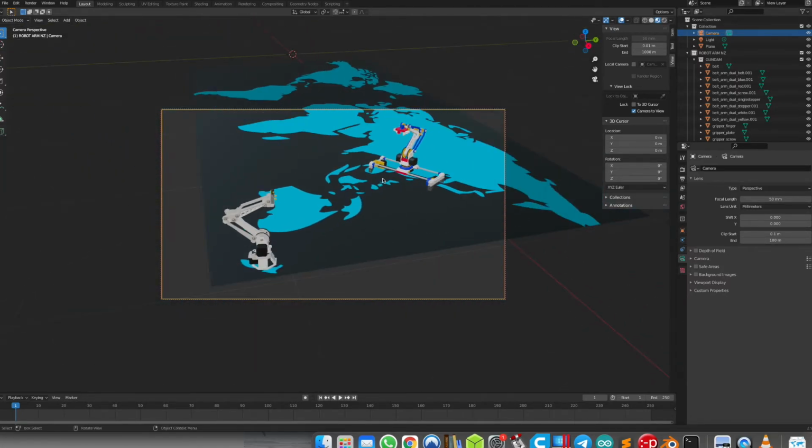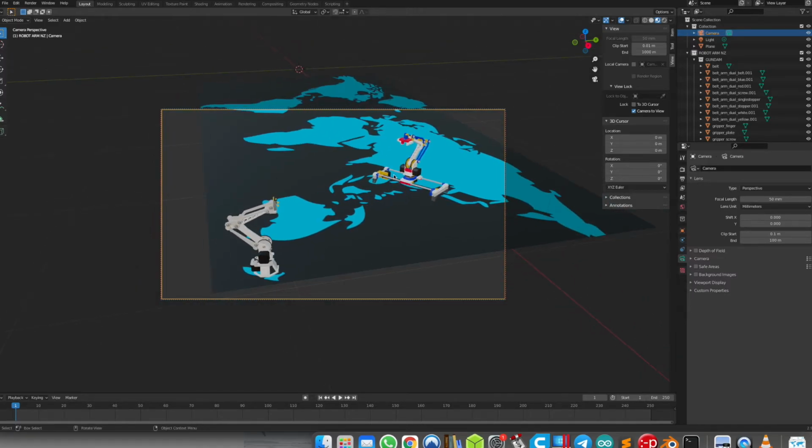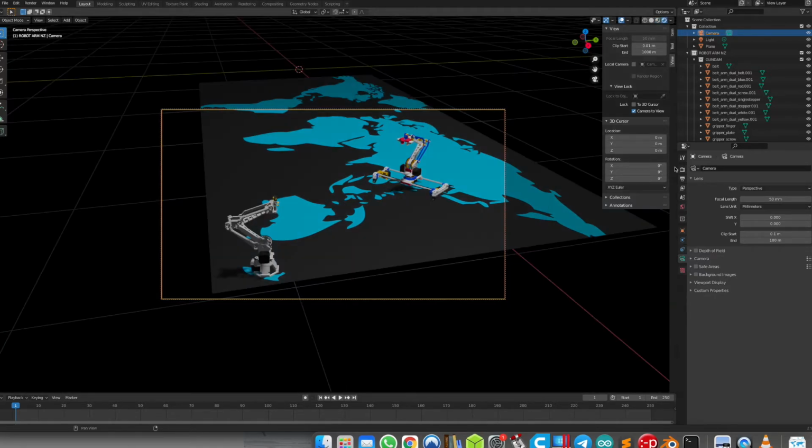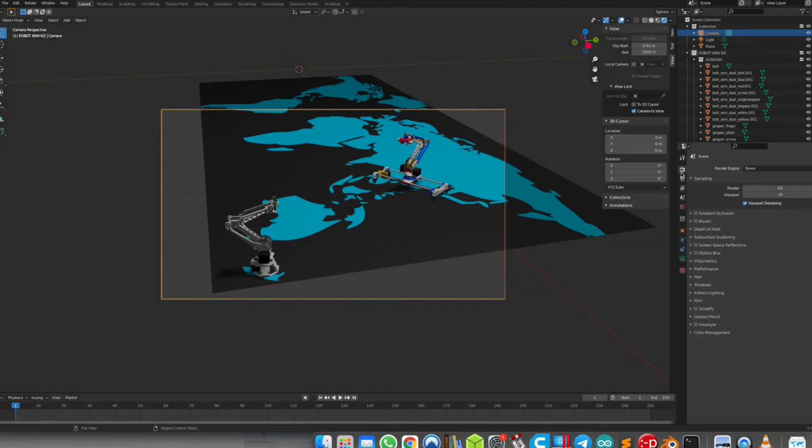So far we have been viewing our screen in material preview mode. We can start a preview in render mode to get a simplified glimpse of rendered results on screen. Here we click Render Properties. We can raise the render value. In this case, we'll raise it to 128 to improve the end result quality of the render image.